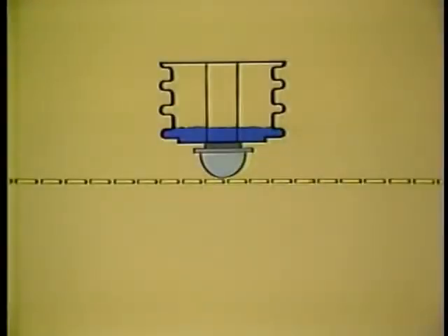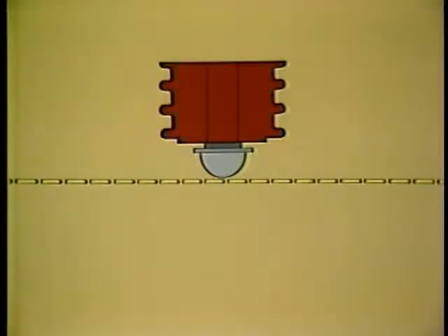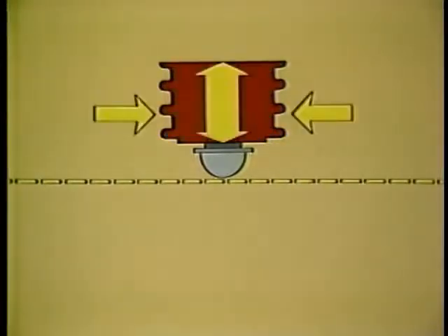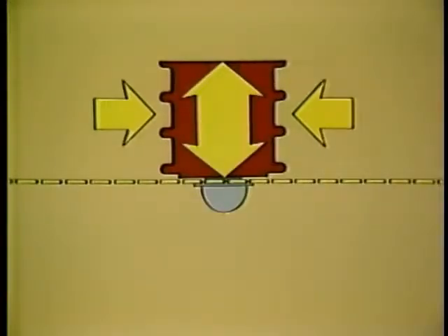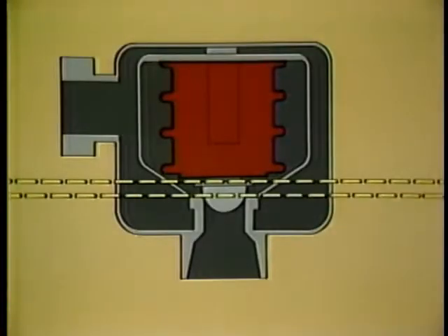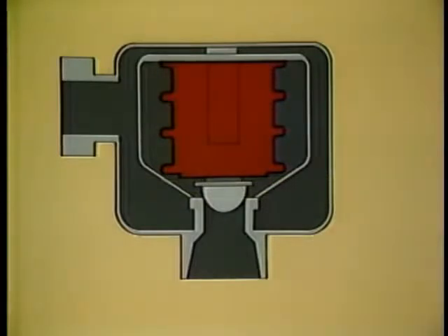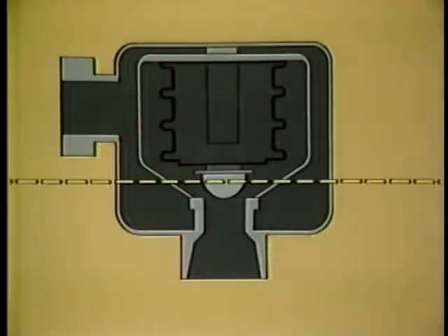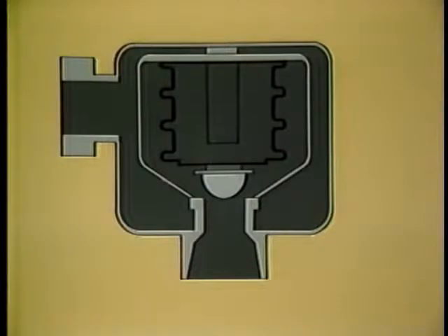In traps that will fail open, a mixture of alcohol and water is commonly used as a charge because it will boil just before the saturation temperature of steam is reached. At any temperature above this point, the internal pressure of the bellows will be higher than the system pressure. With this higher internal pressure guaranteed, the valve seat for these fail-open traps is placed so that the bellows extends slightly beyond its free length to seat the valve. If the bellows is ruptured, it returns to its free length and the valve opens slightly.